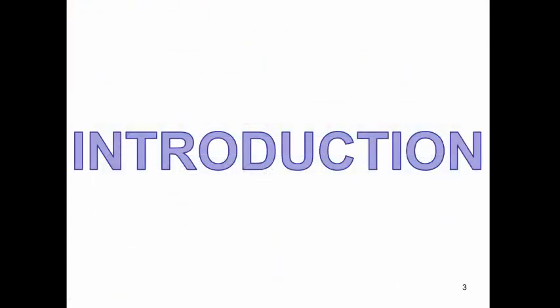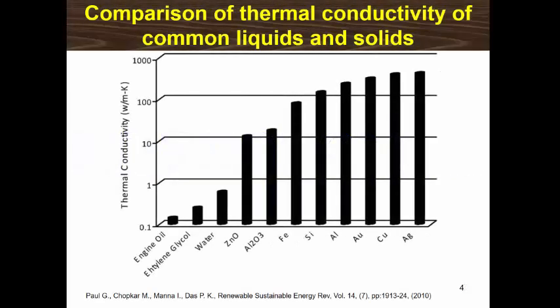Efficient heat transfer systems are an obvious current and future need of many industries, such as microelectronics, transportation, space, and defense. There are several methods for heat transfer enhancement. One of them is to improve the thermal behavior of heat transfer fluid. As shown in this figure, thermal conductivity of most solids is orders of magnitude higher than that of most heat transfer fluids. So adding solid particles to the fluids improves their thermal conductivity.